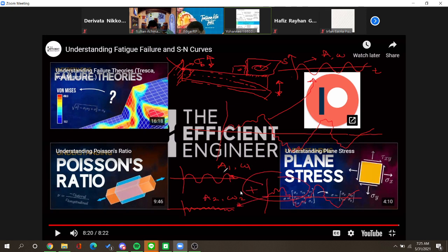If we are able to do this, then we can analyze the fatigue failure for each signal. So here we have several vibration signals or several fluctuating loads. So how do we apply Miner's rule on this type of load?